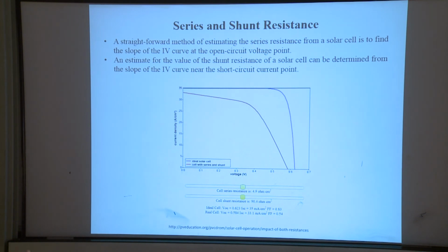The fill factor is a parameter to see the effect of parasitic series and shunt resistance, right? So I can also answer the question that one student asked previously. Fill factor is also a parameter to see if we have carefully done the process for the solar cell.